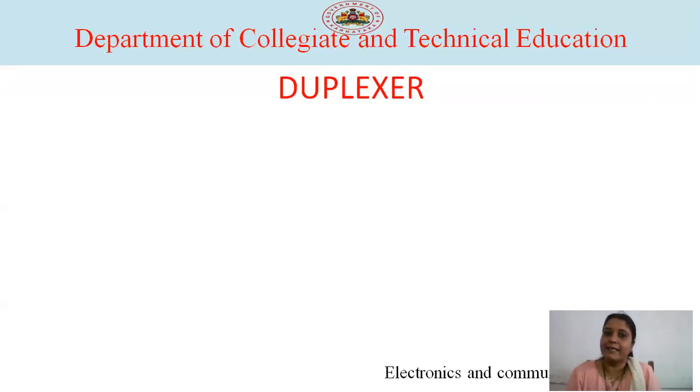The duplexer takes care that during the transmission process, the receiver is temporarily disconnected, and during the receiving process, all the echo signal energy is delivered to the receiver section, not to the transmitter section. That is one of the main tasks of the duplexer.